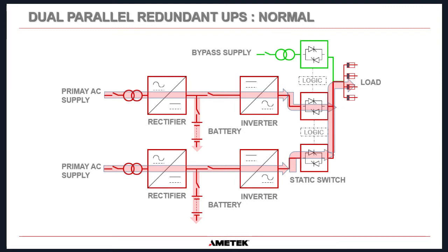And that takes complex logic, because you've got to understand that there is power factor involved, there's leading and lagging issues. So we have to take care of all of those issues to prevent circulating current between these two UPS systems. So it is very, very complex to connect two UPSs in parallel.